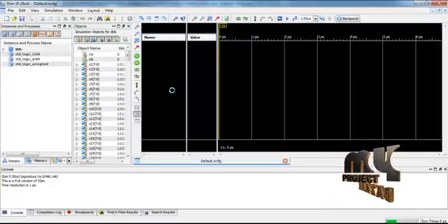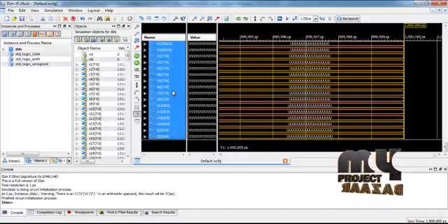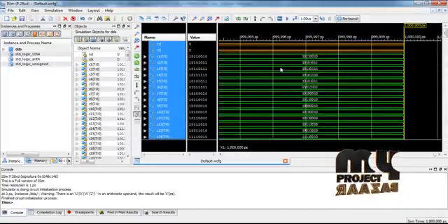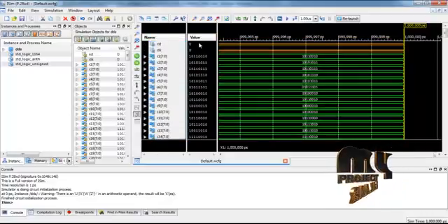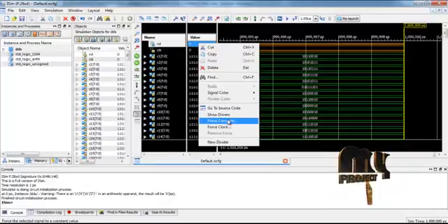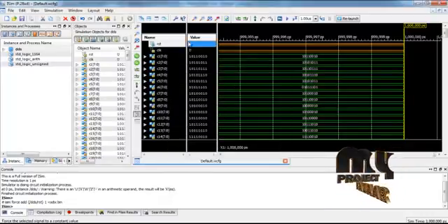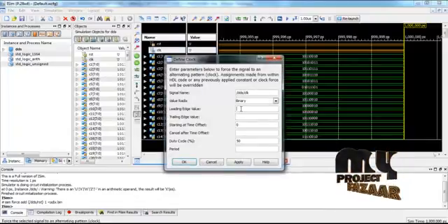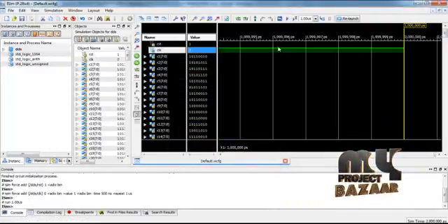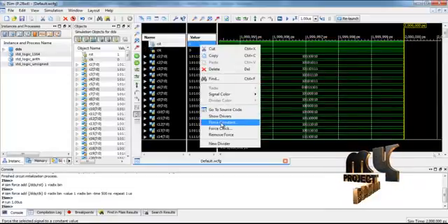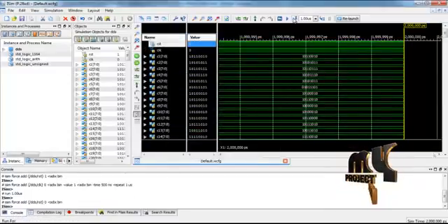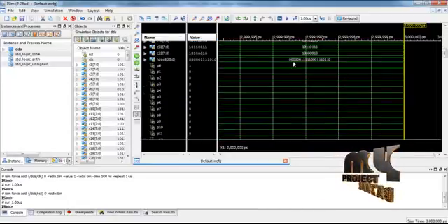Then we apply the input data signal and the clock enable signal for the trough detection based 32-tap FIR filter functionality. These are the final output functions. We have already applied the coefficient signals, and we apply the clock one by one for data passing to the overall architecture. Then reset equals 1 and we apply the clocking signal, then remove the reset signal and pass the data for the shifting operation in the overall 32-tap FIR filter architecture.